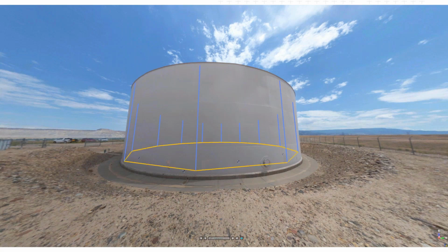Once you do that, you'll start to take horizontal measurements, getting the circumference of the tank, and you'll start measuring near the bottom, near the shell to bottom weld. The way the tanks are built, if you look here at the image, you'll see these tiers like a wedding cake, where you build a tier at the bottom, then move up and build another tier, and so forth until you get to the top. These are known as courses, from one weld to the next.